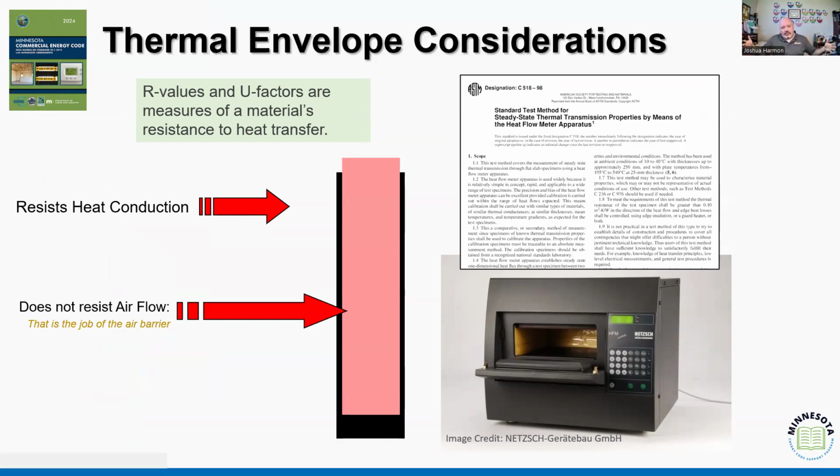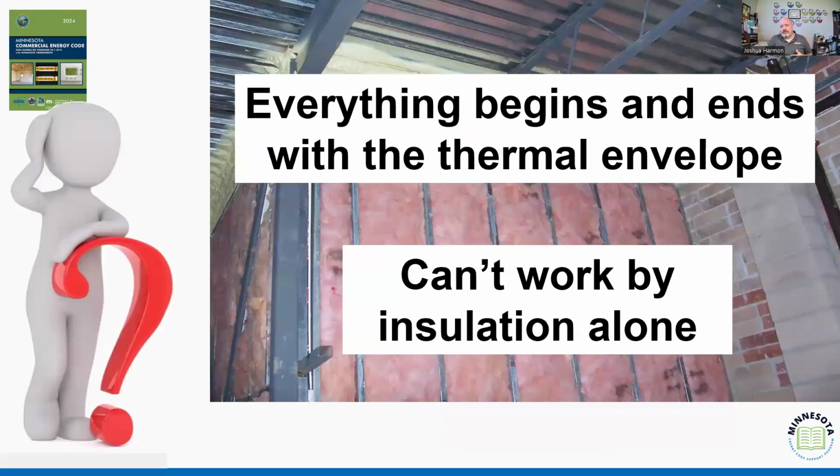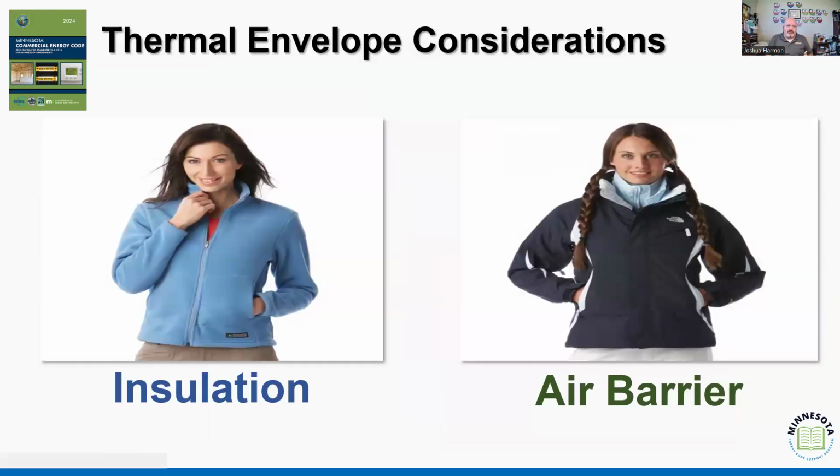Because of inadequate wall insulation or because of inadequate air barrier controls, right? And so again, while everything in that conversation about thermal envelopes usually starts with insulation, it's not insulation alone. It's that relationship between the insulation and the air barrier, right? And so when we start to think about that, one thing that I usually see, and I'm going to do